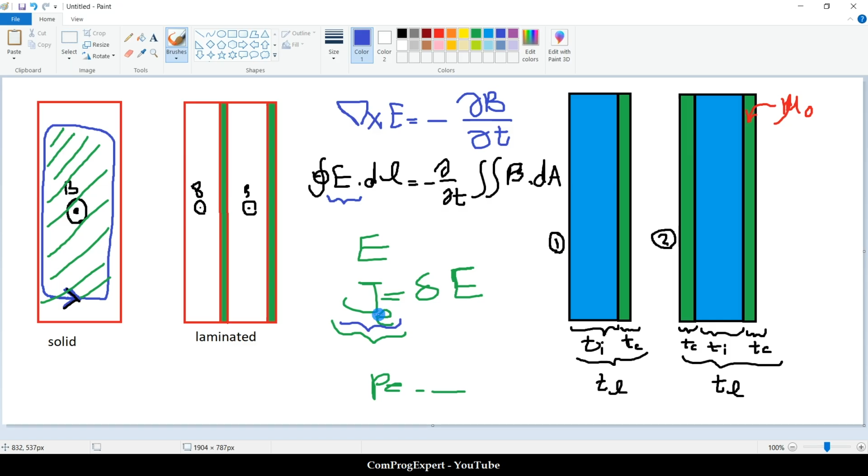How can we reduce the amount of induced eddy currents? If we use a laminated core and use insulation coating between laminations, we can, for example, in this case, divide the area enclosed by this eddy current.